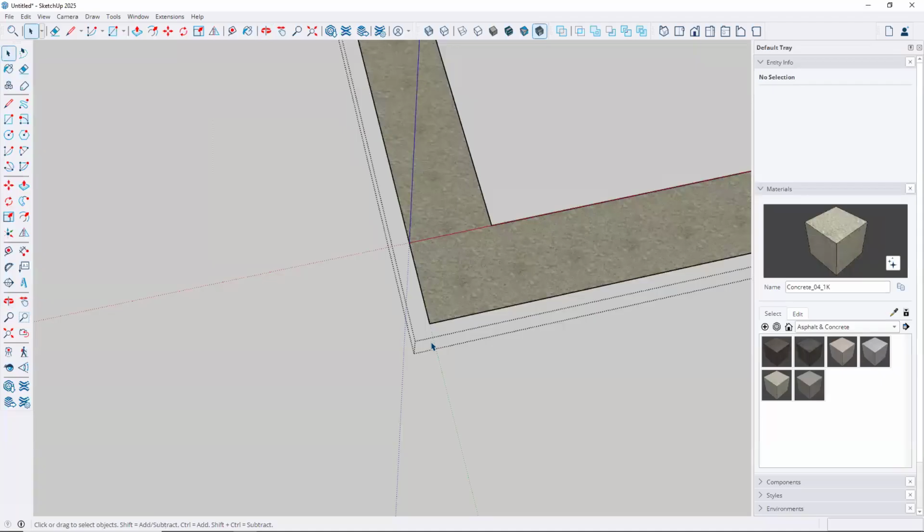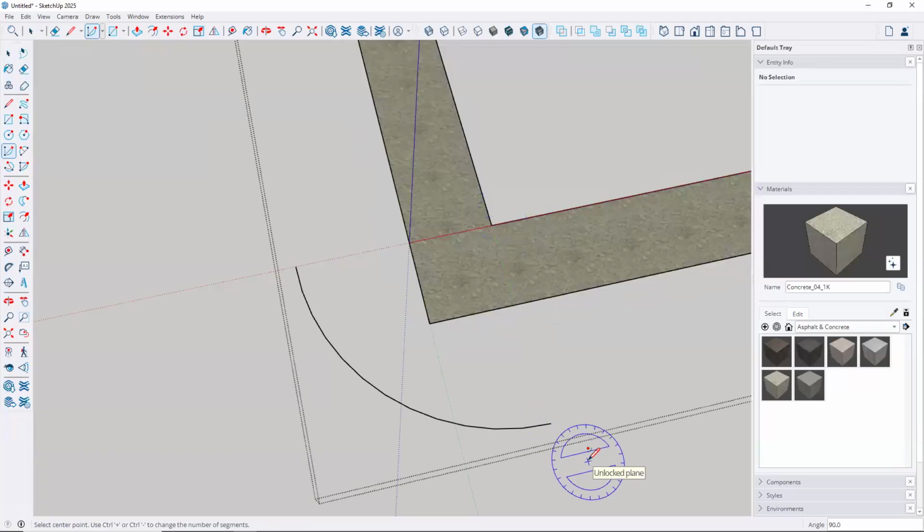And then the tool that I want to use is this one right here where it says draw an arc. So I do want to draw the arc, so I'm going to click on that. And then before I start drawing anything, you'll see where it says number of sides 12. Now watch this. If I draw an arc, and I'll just start right here, I'm going to do this real quick, nothing specific. I'm going to start drawing it this way, and I'll stop right there. Just want you to see something here. There we go. All right, that's an arc.